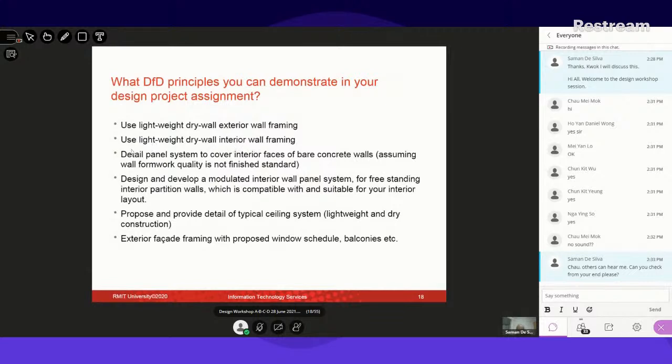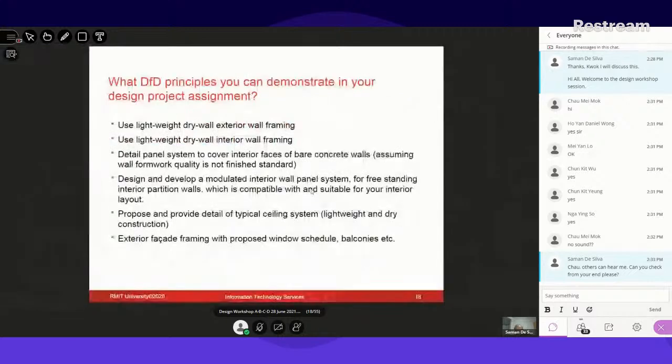One thing is that those walls weigh very heavy. If you design a floor slab to sustain a block wall like that, you have to make sure there's a beam going under, or a design that you don't put those types of things right on slabs. You can do that, but then you have to design for that dead load, which is relatively heavy.